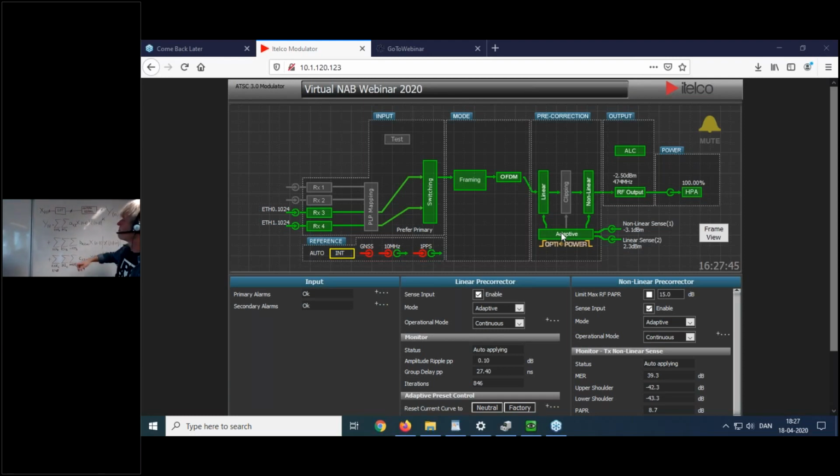I will make it short. So this is not a complete Volterra kernel. This is something that we can practically do in our machine. We save a lot of the complexity by taking the majority of the nonlinearity in a lookup table. Then we follow the lookup table with the Volterra kernel. And the Volterra kernel we have made is what we call a truncated kernel. So we don't run indefinitely long in all dimensions, but we have a subset of that.